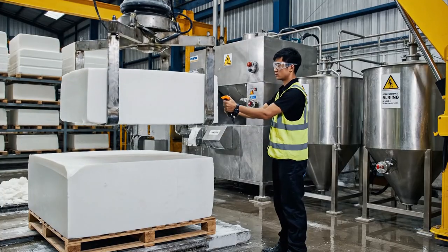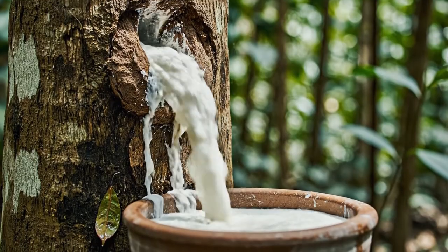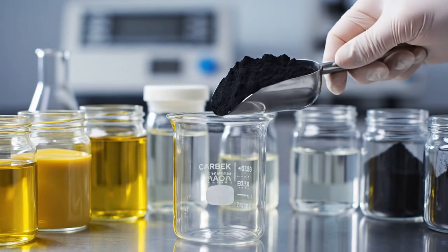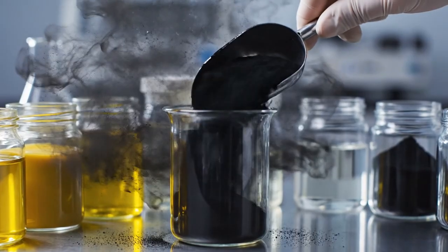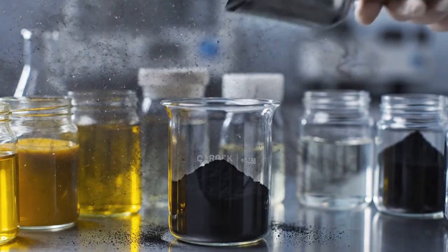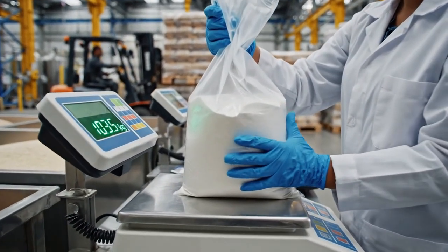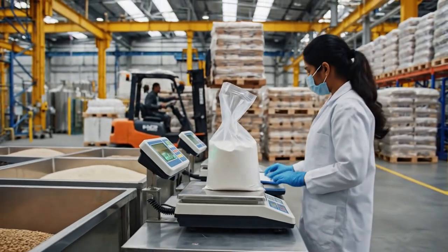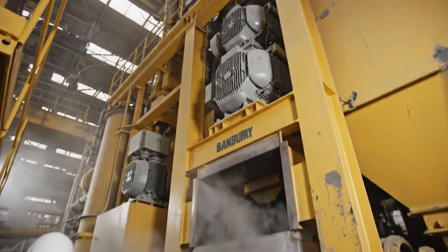After the design is approved, manufacture can finally begin. The modern tire is made up of 10 to 15 different components, which include natural and synthetic rubbers, chemical additives, and carbon black, a pigment. These materials are delivered to the factories in rail cars and are transferred to storage. Then, computer systems measure out specific batches of rubber and chemicals for mixing, which are then sent into a Banbury mixer.